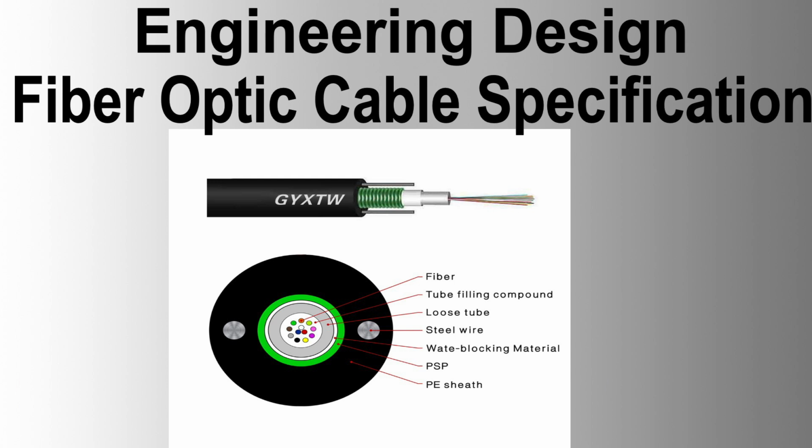Testing requirements. General. Provide test reports for the IEC 60794-1 series of cable tests noted below. The tests must have been performed on an identical or similar construction to the one being offered, and with equal or higher fiber count. In the absence of pre-existing test reports, the cable vendor must perform the tests on an actual length of cable manufactured and shall submit the type test reports to the purchaser for approval.